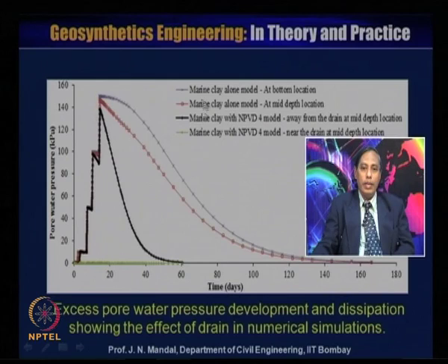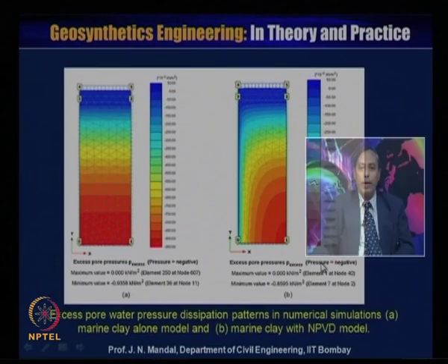You can see for the different locations what the pore water pressure variation is with respect to time. The pore water pressure is increasing up to maybe 20 days, and then it abruptly decreases with increasing time. So, you can have an idea how the pore water pressure varies with time.